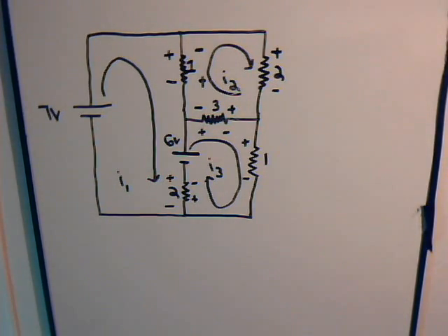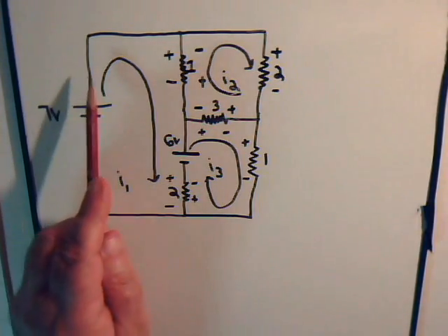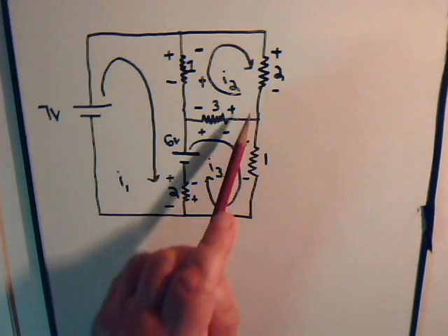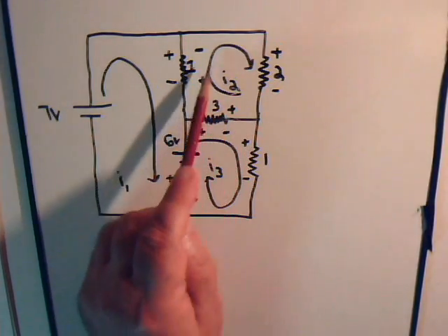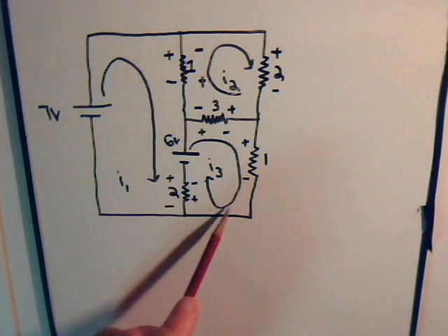That certainly is true, and if so, it will reveal itself later when we do the number crunching part. But to set the problem up, we look at each individual window of the circuit, and we draw it as if there is a clockwise current flowing through that window.